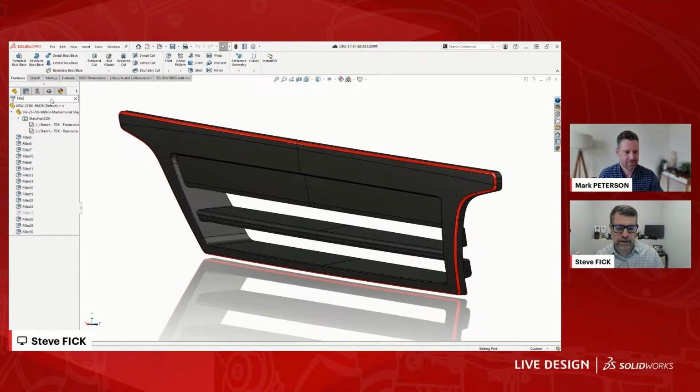But I want to pair this with another feature that I don't know that people also use a lot. And that is tagging. What tagging allows me to do is select a feature, and then down here in the right-hand corner, I can hit this little tag button and give it a tag, and any tags that I've used show up there. So in this case, this is a cosmetic fillet. So I'm just going to select that as the tag. And once I do that, that then also is searchable. So if I type in cosmetic, immediately the 3 fillets that I've tagged with that now show up.